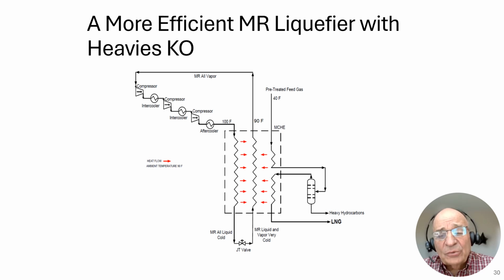And what else could we have done? Well, we could have improved the efficiency of the heat exchangers, but that's another balanced engineering decision that has to do with looking at whether you're going to increase your capex so that you can decrease your opex. What else can we do? Well, we can take the boil off gas off the tank, and it's cold. Take that boil off gas and use that as refrigeration in this process as well.